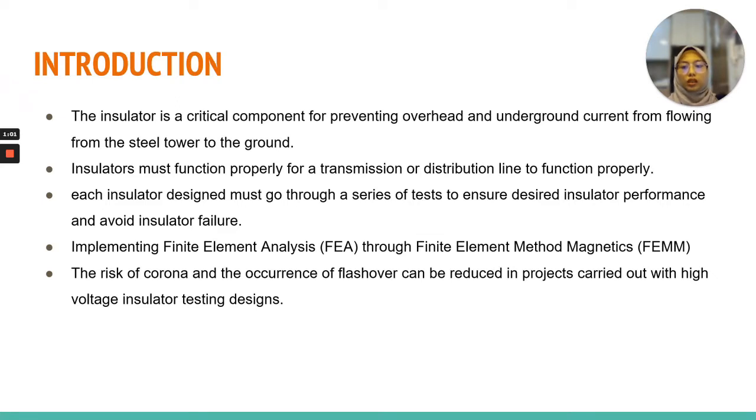Implementing the finite element analysis, FEA, through the finite element method magnetics, FEMM. By using FEA through FEMM, the method of computing potential difference and electric field disturbance is carried out in order to provide information on the state of our insulation design. The risk of corona and the occurrence of flashover can be reduced in this project, carried out with high voltage insulator testing design.